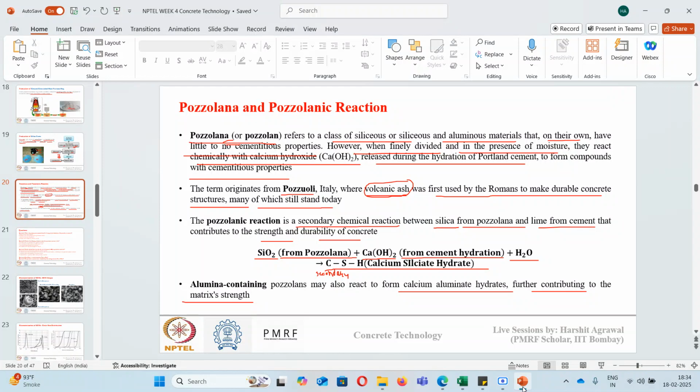Sir, when we are going to produce concrete, concrete is basically an alkaline material. So it is having a pH value of more than 9, right, sir? Why is concrete alkaline? You can tell me the reason. It is because of the alkali ions which are there in the pore spaces. It is not because of CSH.